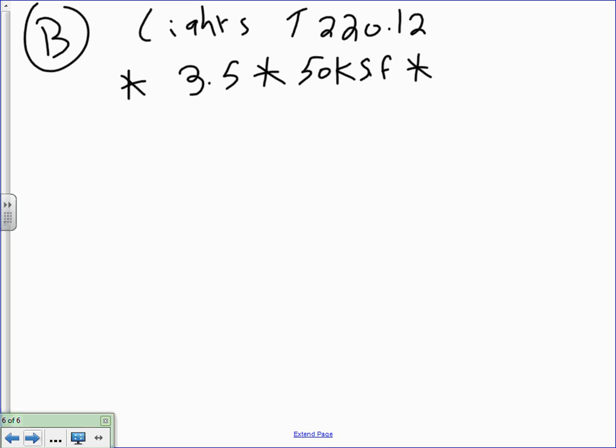I'm adding the continuous load, the 1.25, directly into this step. Multiply it directly in this step. You could multiply it at the end, or you can multiply it right here. So what's my outcome for this step? My outcome would be 219.